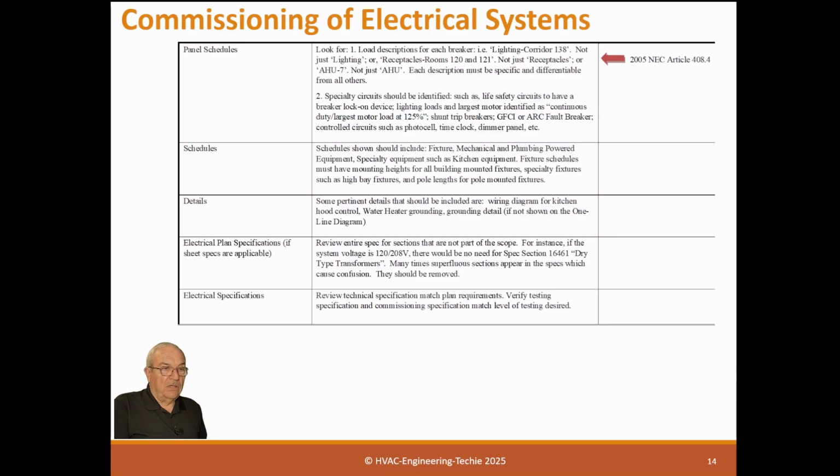And electrical, a lot of times, fail that. For instance, if you have a hydronic mechanical system that has a cooling tower, you will almost never see a wiring diagram for the water treatment equipment, which takes 110 volts. So it should have a wiring diagram. A lot of times that's just left in the open. And you get down to the job and then no one's got the wiring in, so now you have to figure out who's going to do the wiring and is it an extra or not. Things like that should be included in electrical.